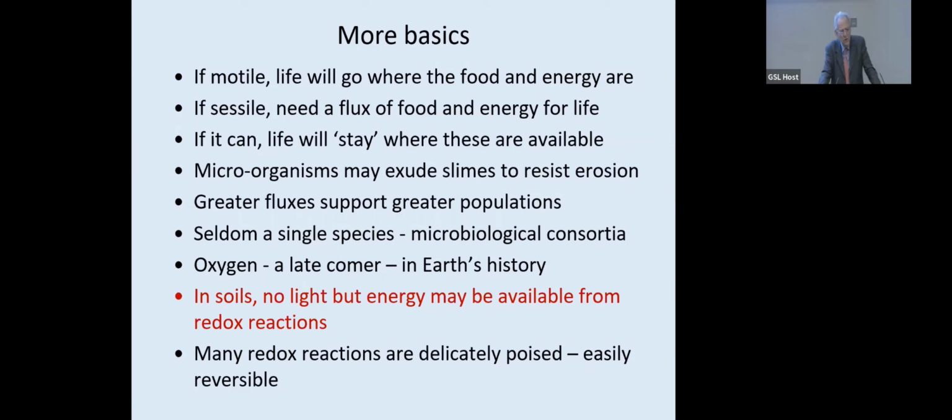And just remember, almost all the soils we're going to come across were laid down in an anoxic environment. Oxygen was very much a late comer, wasn't it, in the geological history? And in soils, of course, there's no light. So the only available energy in soils for microbiological life is redox reactions. So that's the crunch. We've got to look at these oxidation reactions. They are what are going to power any microbiological change, like the generation of mercaptans. But one of the problems is they can be delicately poised, means they can balance one way, balance the other. They can be reversed. Other microorganisms can come along and use that to go the other way, provided there's some other energy source to enable that.